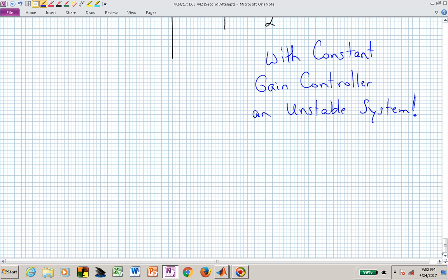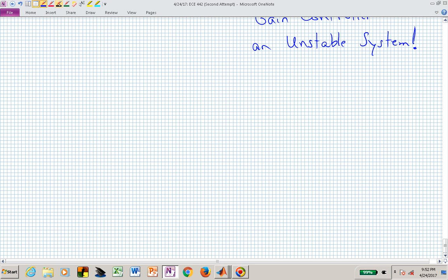So let's take out another napkin if we're in an interview and trying to figure out how to stabilize this system. It was an unstable system because that pole at 1 is marching off to the non-minimum phase 0 at 2. Now what we want to do is again try to get rid of always having a branch of our root locus between 1 and 2.